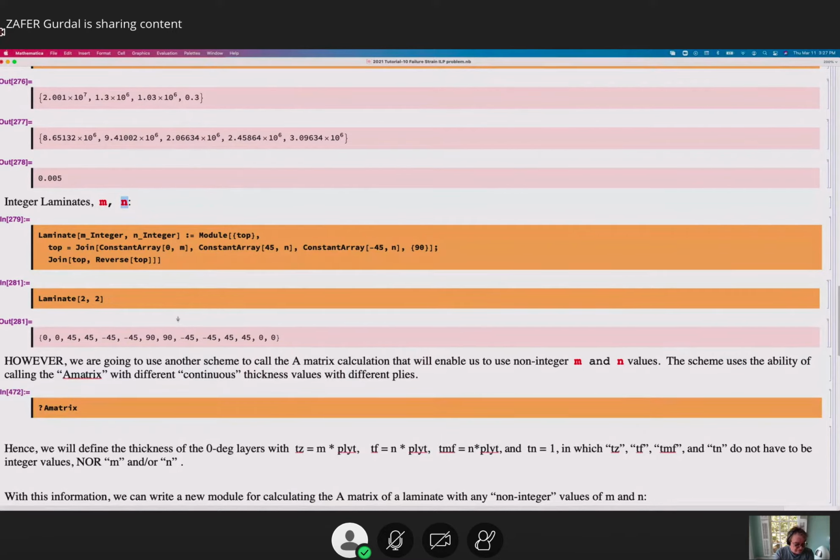So this is something that I have not checked: if Mathematica will work for integer design variables that have functions defined in terms of them that are continuous. But that's easy to check. You can put an objective function, which is something like 2.5 times the integer variable. And if it can evaluate the objective function, that's great. If not, that's a real problem.